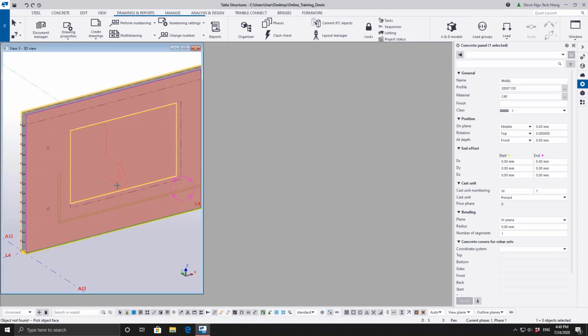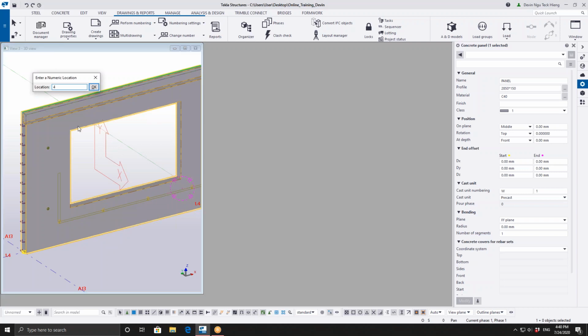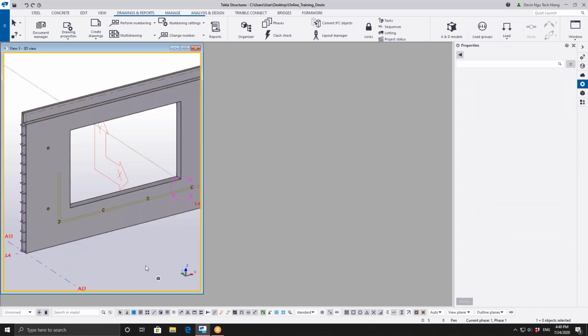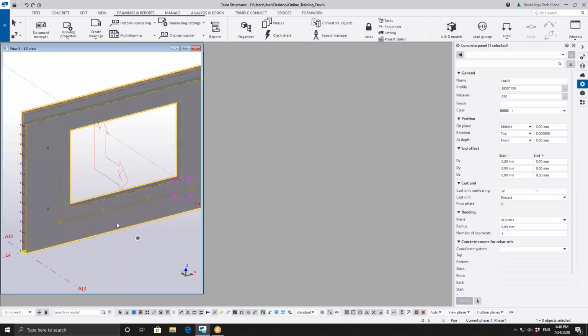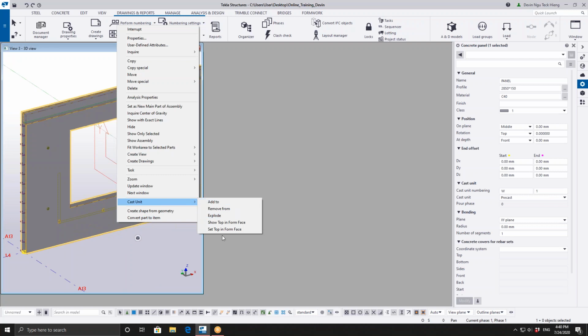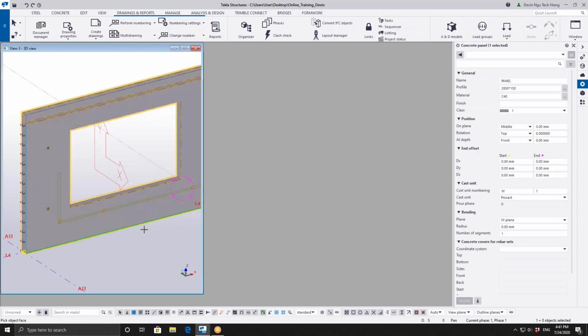All right. So first of all, let's fix your UCS. Okay, object not found. Can you press Control 4? Control 4, and then click the surface. Yeah, now you click the surface.